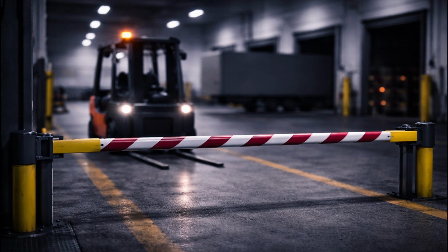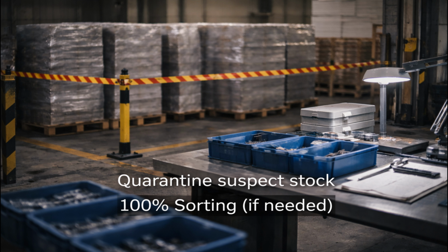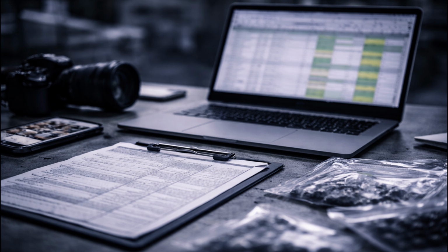Stop shipments. Quarantine suspect stock. Start 100% sorting if necessary. But careful, here's the important point, the clean point. From this lot number onward, every part has been verified and is safe. Can you say that with evidence? Are your lot lists, photos, and data ready?